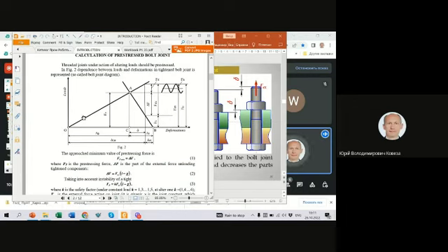Here you see this bolt deformation, this line is joint deformation. And after the loading by external load, we have such state that two not equal forces: Fz, this force additionally loads bolt, and delta F, this force decompressed joint.